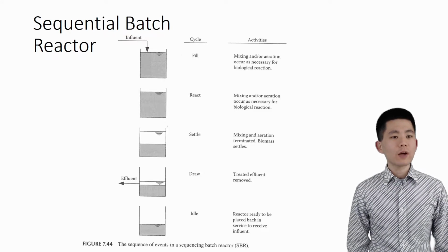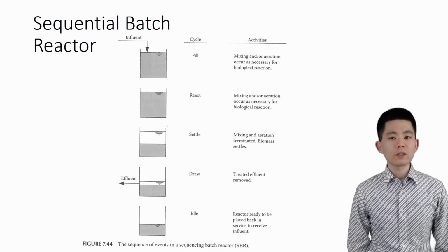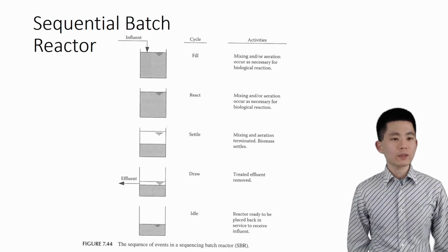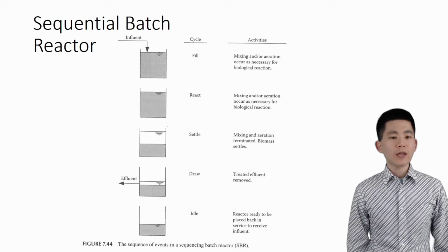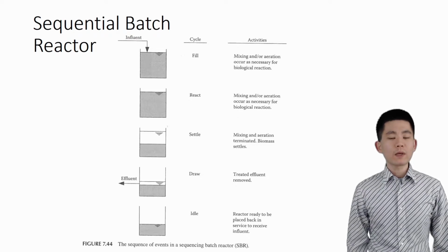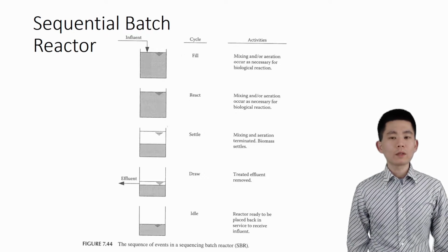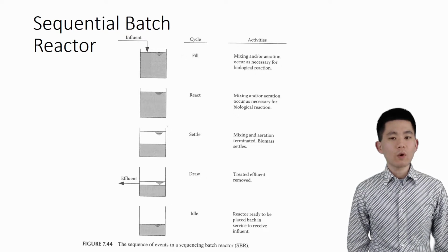Typically, several SBRs are operating at different stages in parallel to receive a continuous influent. SBR can be quite flexible. To achieve nitrogen removal, it can mimic the MLE system with one anoxic aerobic cycle or a four-stage Bardenpho system with two cycles for a high effluent quality.